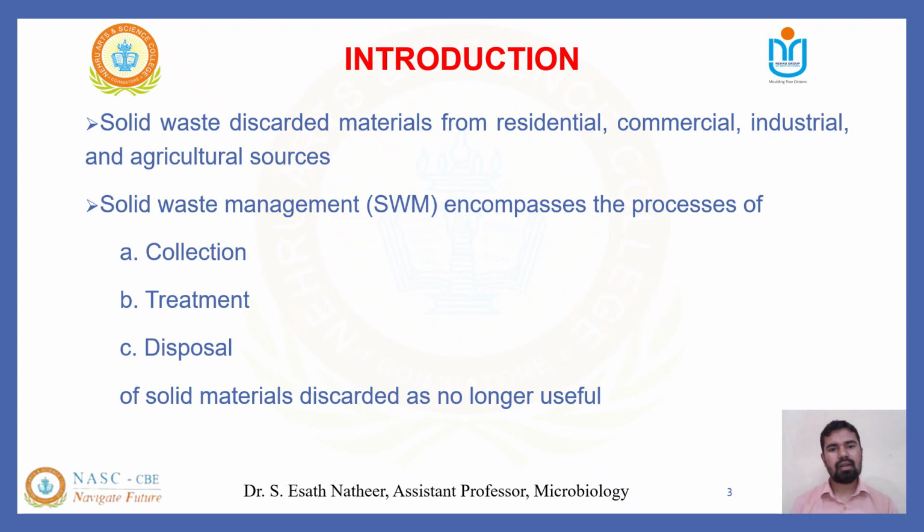Solid waste is the discarded material from residential areas, commercial areas, industries and also agricultural sources. Solid waste management encompasses three different processes. The first one is collection of the waste from the source, and second the treatment. Treatment is done by chemical, physical or biological means. And finally, the disposal of solid waste should be done at a proper location, and if it is not being used for any purpose, it may be dumped deep into the soil